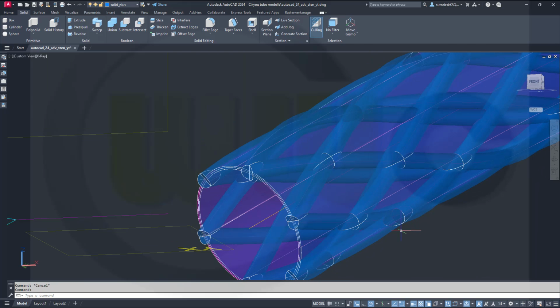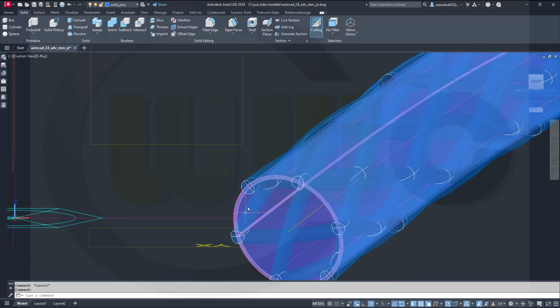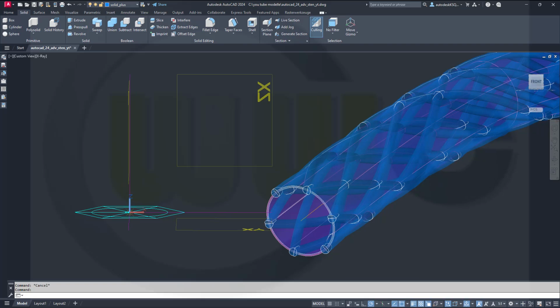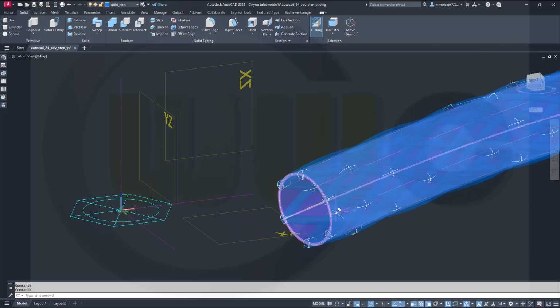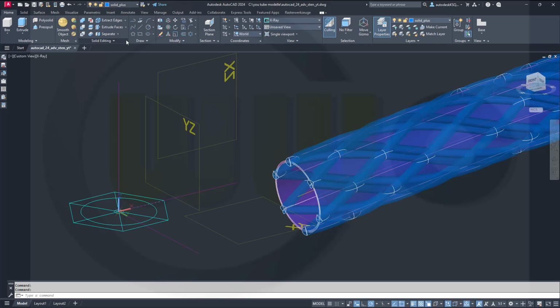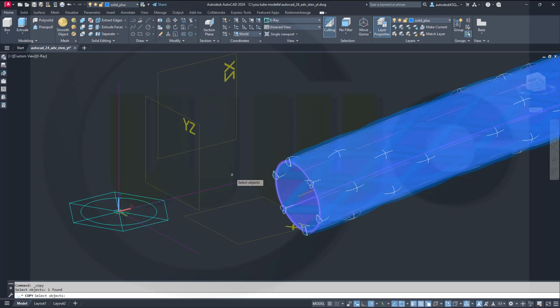And now I want to intersect that surface with those, not surface, but this solid with the other two solids. Therefore I will need a copy of that one here. So let's go to Home, go to Copy. There you go. Select that solid here, the 3D solid.